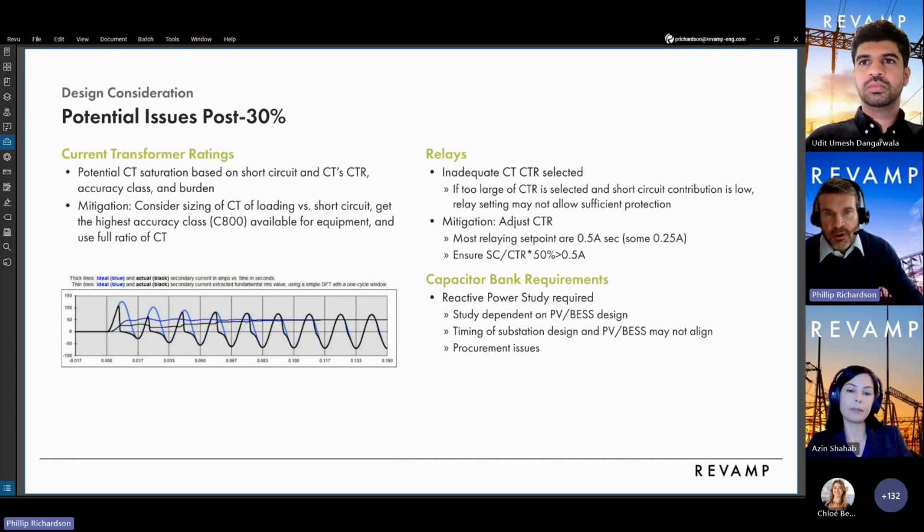This can cause the relay to be slow to operate, which, based on the total clearing time required to protect equipment, may cause equipment to be damaged. Also, if a CT that is connected to a transformer differential or bus differential saturates, it may misoperate. It may trip for faults outside of its zone of protection, thus tripping off more devices than is needed to clear the fault.